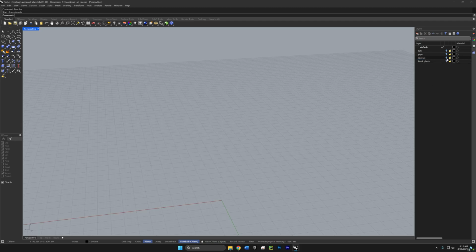Next, we'll work with the revolve layer. So we'll click on this light bulb. We'll use the lasso to select both of these polycurves, and then we'll type in revolve. And the start of the revolve axis is at the top. We need to temporarily turn our OSnaps on, so I'll hold down the Alt key to temporarily toggle OSnap. And on the left, we want to make sure that the end snap is enabled. And so the start of the revolve axis that's being asked for in the command line will be here, and the end of the revolve axis will be here at the bottom.